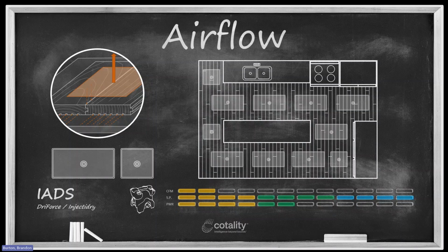Now, in terms of plumbing them together, what I would do to get the best efficiency is to put my blower in the middle of my chain of mats. So take your eyes to the mats that you see running between the sink and the island counter. You'll notice there's one small mat up by itself in the upper left of that floor. And then we have a run of 4 mats that go right in between the island counter and the sink and the stove. My blower would be right in the middle of those mats, and then I would tee my hose and run in both directions. In other words, draw evenly from both sides.